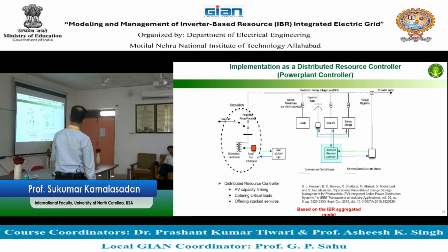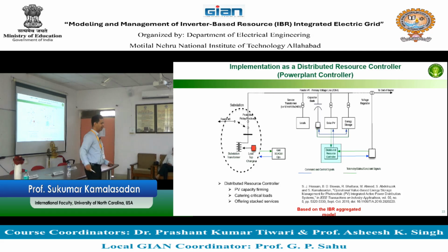This is generally called power plant control, a term I started seeing when I was in IISc. In India, a lot of people are now talking about power plant control. The power plant controller is basically this control that sits below the management system of the utility, locally taking care of the PV farm output as a collective PV farm output.